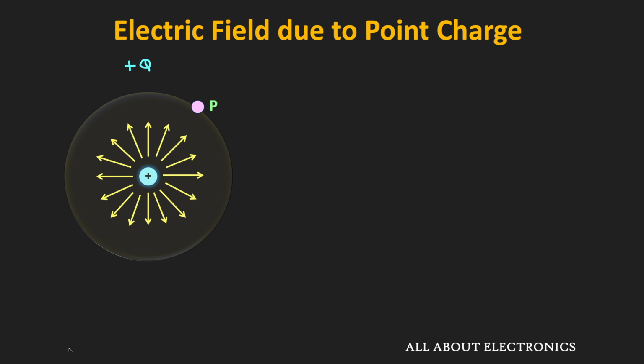So now, as per the Gauss law, we can write the following expression, right? That means the surface integral of this D dot dS is the same as the charge that is enclosed by this closed surface. And in this case, this enclosed charge is equal to q. Now here if you observe, at any point on the spherical surface, this electric flux that is going outward from the point charge is normal to our chosen surface. Or in other words, the area vector of our chosen surface is in the same direction as the D field. So therefore, our dot product will become the multiplication.